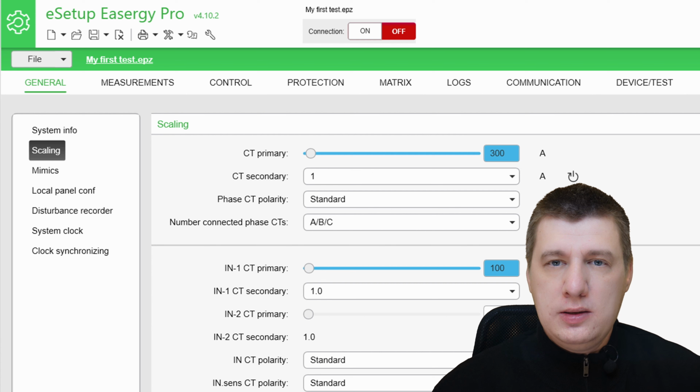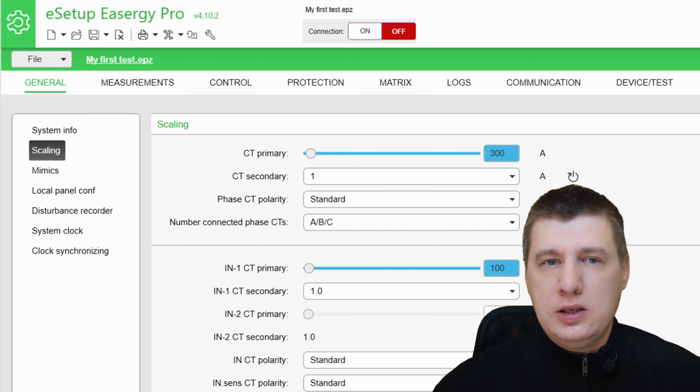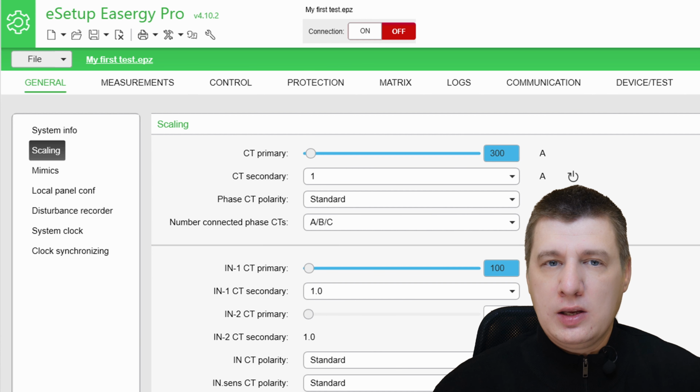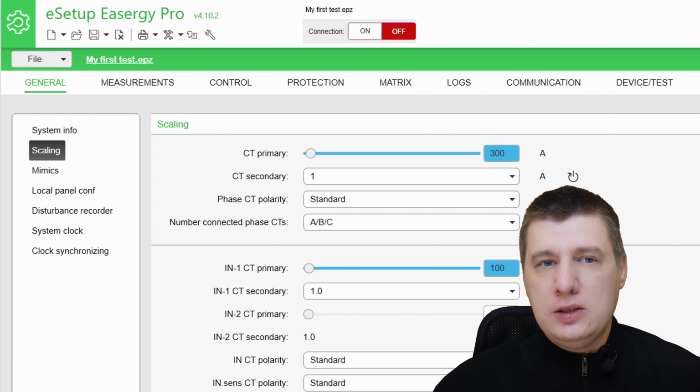In the protection relay, scaling is the essential process of converting the low-level electrical signals received at the device terminals into the actual high power values present on the electrical network. It ensures that the relay understands the real-world conditions it is monitoring so that it can perform its metering and protection functions. Scaling is used in three simple forms within the relay.